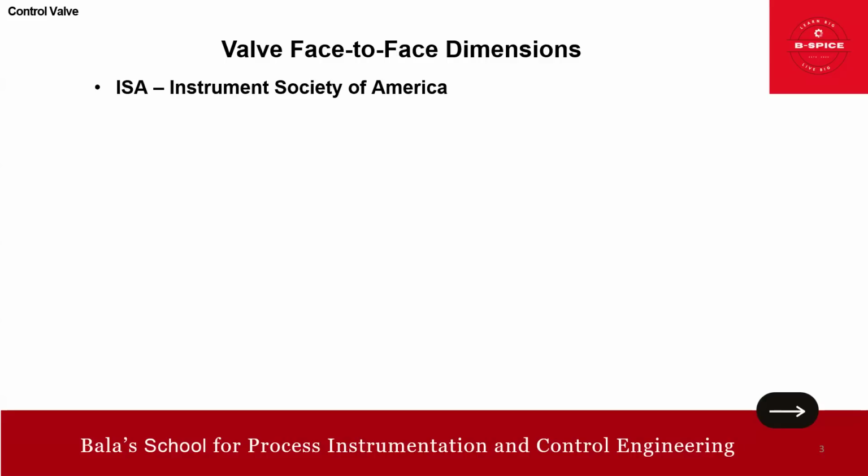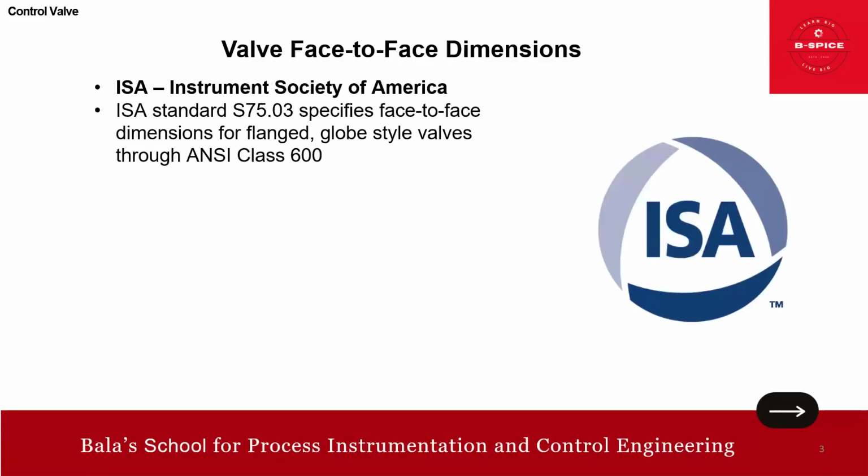Okay, ISA, Instrument Society of America. ISA standard S75.03 specifies face-to-face dimensions for flanged globe style valves through ANSI class 600.